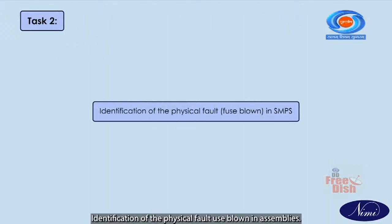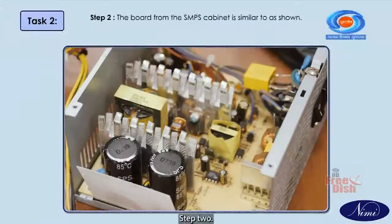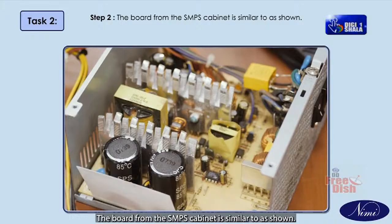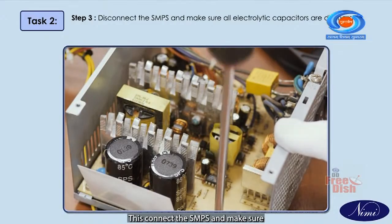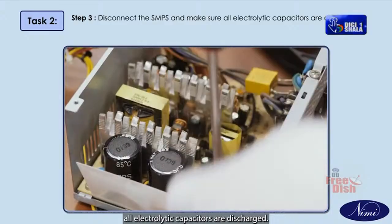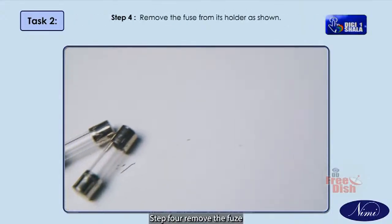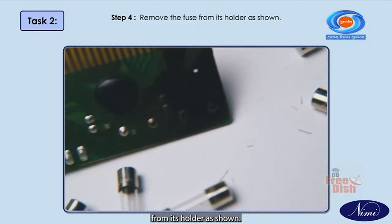Task 2. Identification of the physical fault: fuse blown in SMPS. Step 1. Take the dismantled SMPS as shown. Step 2. The board from the SMPS cabinet is similar to as shown. Step 3. Disconnect the SMPS and make sure all electrolytic capacitors are discharged. Step 4. Remove the fuse from its holder as shown.